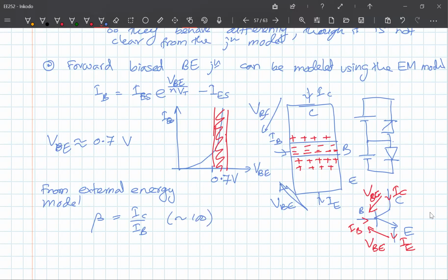There's a large current gain. This is called the current gain, and this value is pretty large. In order to get this, base emitter voltage VBE should be greater than V forward bias of the base emitter junction. So it is typically about 0.7 volts because it doesn't change much. And VBC is less than V forward bias of the base collector junction. So this is a negative level, right?